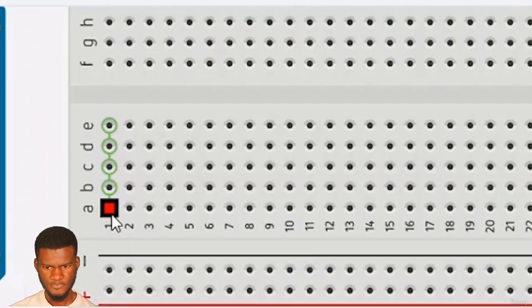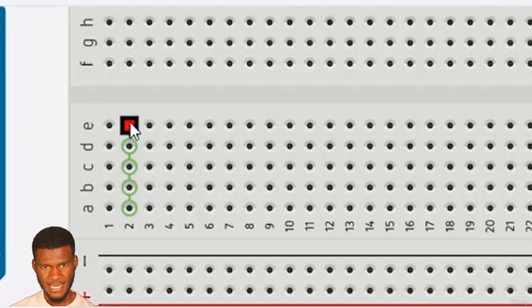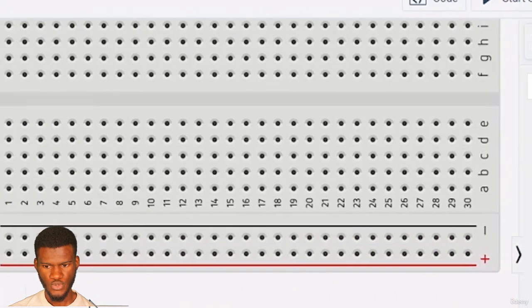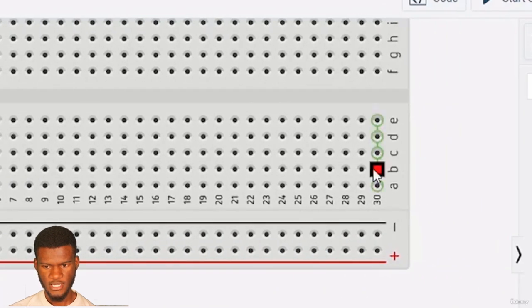I'm going to zoom in a little. Number 2, the second column, is going to be connected. Whenever you plug a wire here, you can tap from that same connection at the last end because this entire column is connected. Same thing goes from 1 to 30. They are all different connections, but it's the same within that particular column.